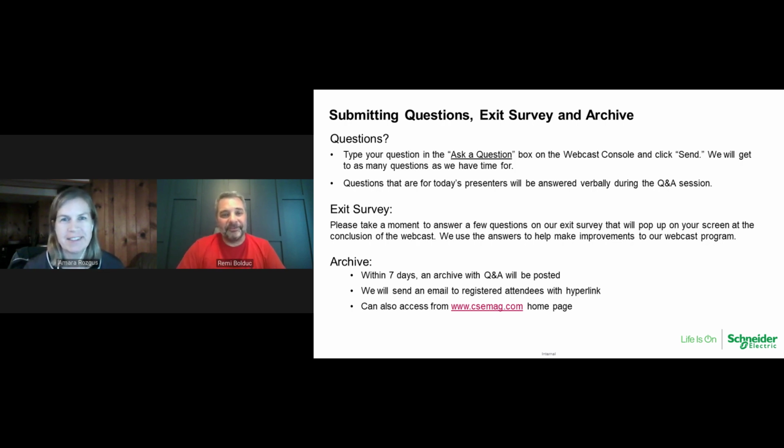Yeah, so we touched on this, so that's a very good question, very much aligned with this presentation. But we've seen variable frequency drives generate high frequency current, harmonics, and naturally capacitors are low impedance to these high frequencies, so they will sink some of these high frequency currents, and it makes them overheat because of the additional RMS current. Also the voltage distortion stresses their dielectric, their insulation, and they will break down quicker, so it affects their life expectancy. So instead of, again, lasting 15 years, maybe they'll last 6 months or a year.